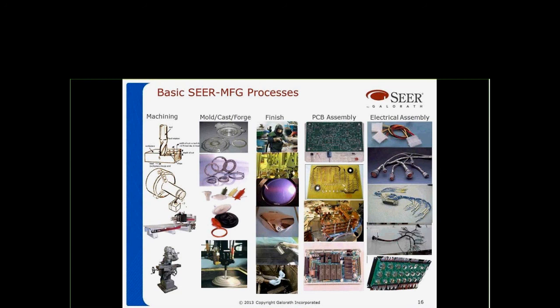And also, you can utilize the machining model in two ways. In a very simple way, where you just tell us how much material is coming away, and the picking operation, and the model does all the work for you. Or you can press the details button and put things in like the axial depth of cut, the radial depth of cut, all your speeds and feeds there. You can actually pick machines, change machinability. You can do whatever you want to do an absolute detailed estimate on your machine parts.